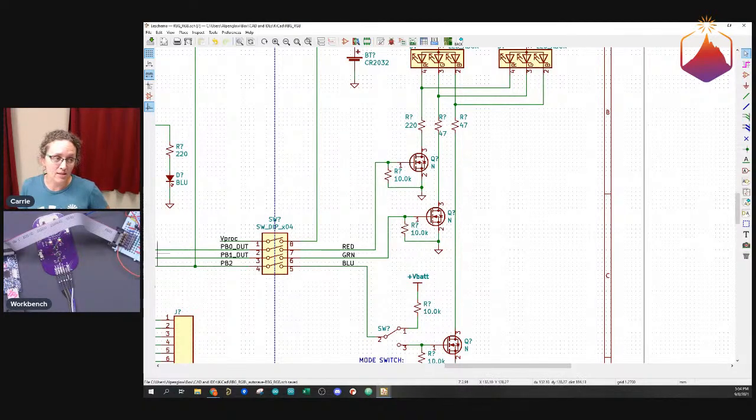So that's what we essentially do with the microprocessor. That's what this signal coming in here is going to be. The pull down resistor is just to make sure that when this is all disconnected from the rest of our circuit, it actually stays off, because these gates are very, very sensitive. When things are just lying around unpowered, they do what we call floating.